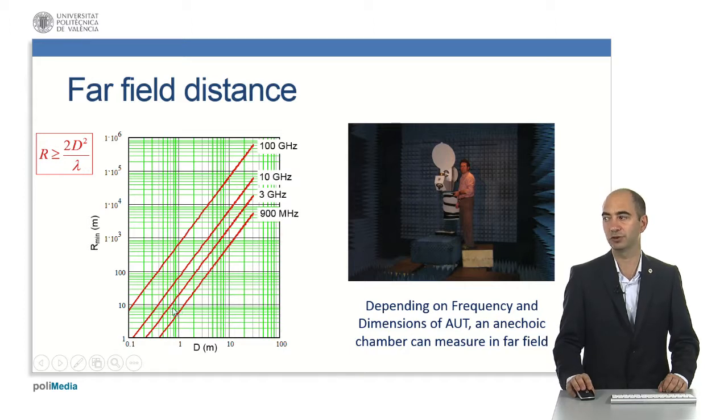Obviously, you can measure in an indoor range the first antenna, but for measuring this antenna, you need big, large outdoor ranges or special systems. Basically, depending on the frequency and dimensions of the antenna under test, you have to be sure that you are in far field. If not, you have to measure in a different way.